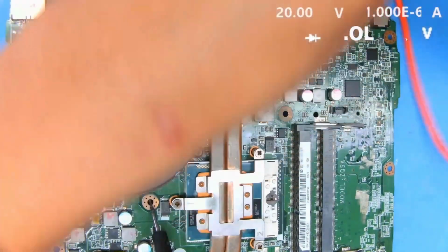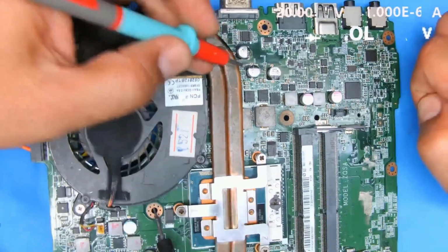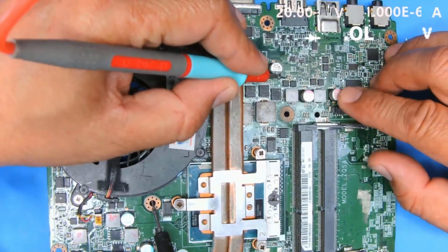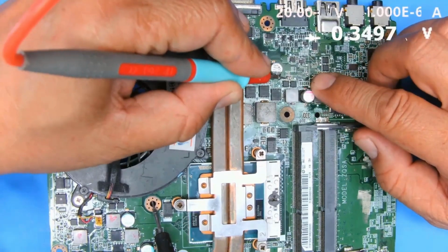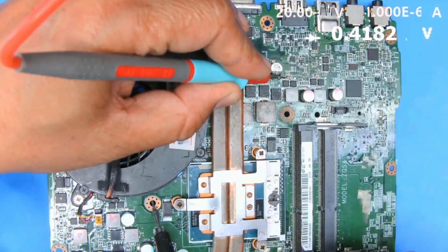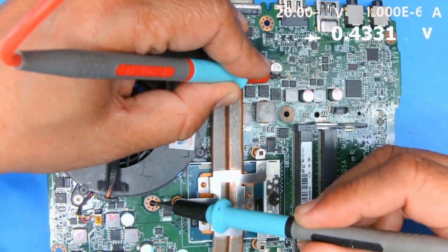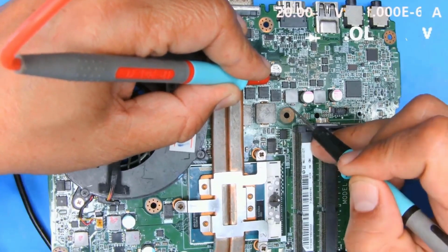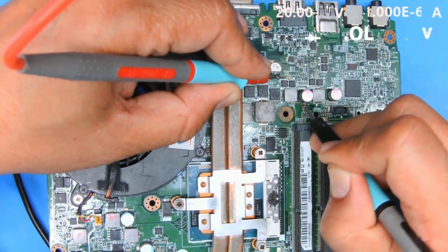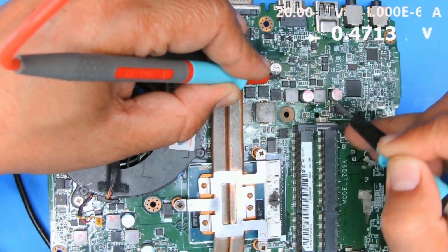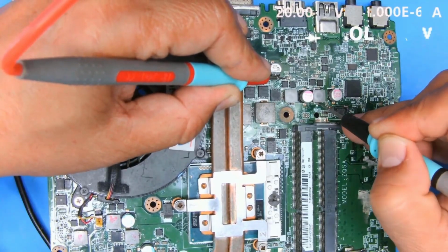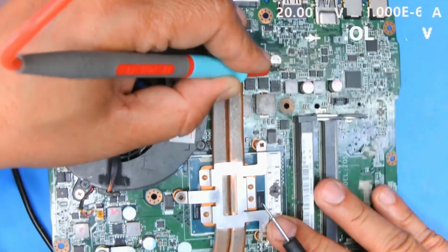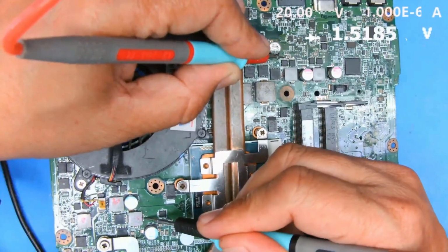Now here's a simple and quick way to measure. We measure between pin 49 and each coil. This pin 49 is already the positive side. Our meter is already set with the red lead on the positive side. Move the black lead away from ground and instead touch it to each coil one by one like this. If it shows 0.2, it passes. If you see a reading of 3000 or so, just ignore it. If the value is higher, that's fine too, just as long as it is not 0. If it is 0, that means that point is where the high drive is shorted.